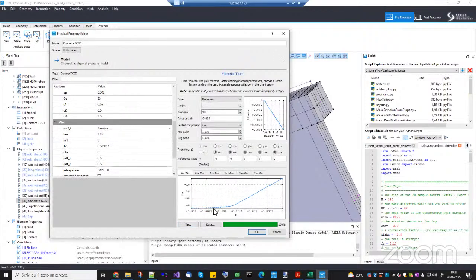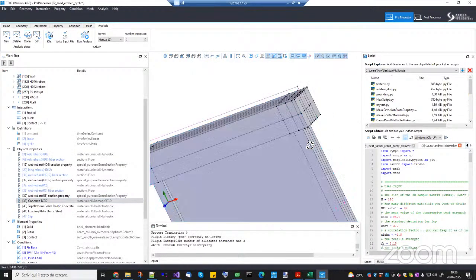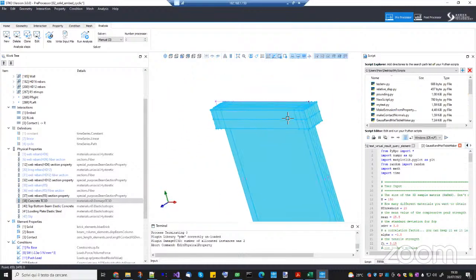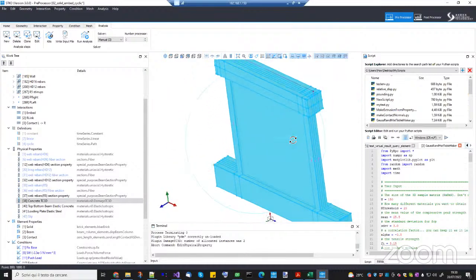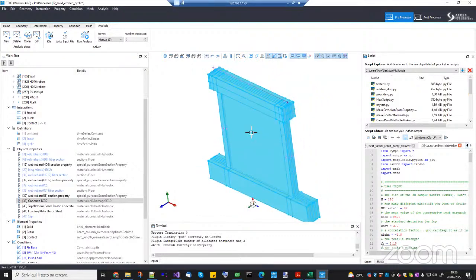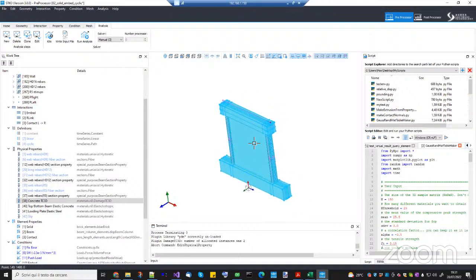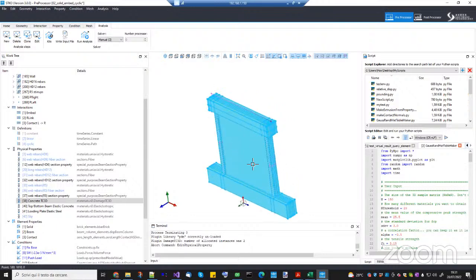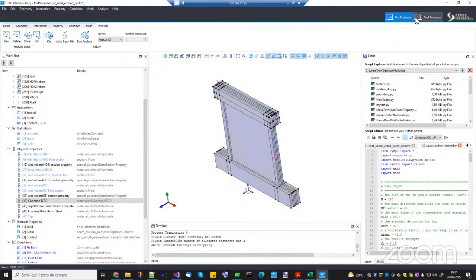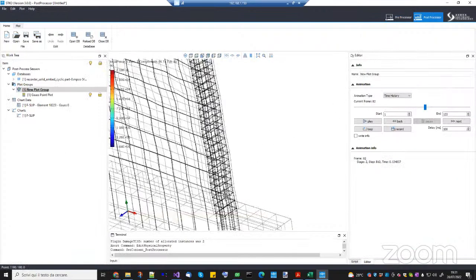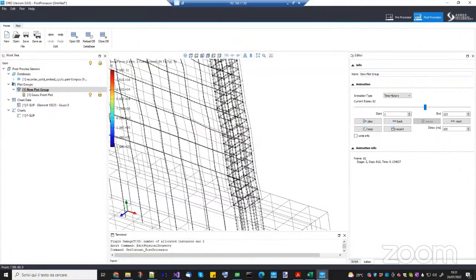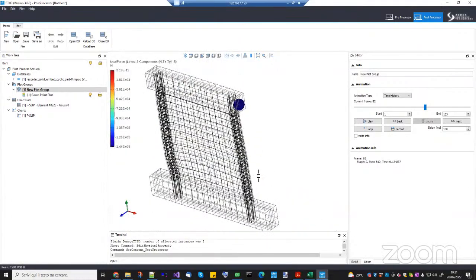Now, in that example, it will not be visible because it was explicitly said that they did not put any vertical load, just self weight, because any added load would have increased the strength of this panel. So they decided to keep the shear strength as small as possible. But yes, using a three-dimensional model gives you also the advantages of modeling the confinement. Yeah, thank you. You're welcome.